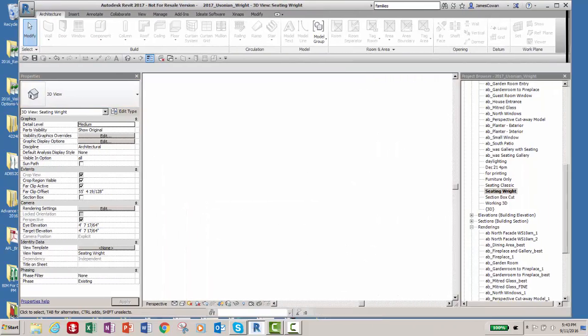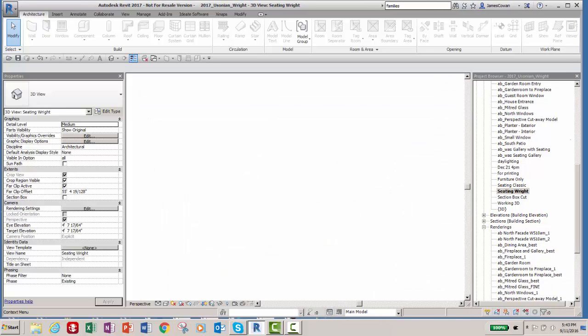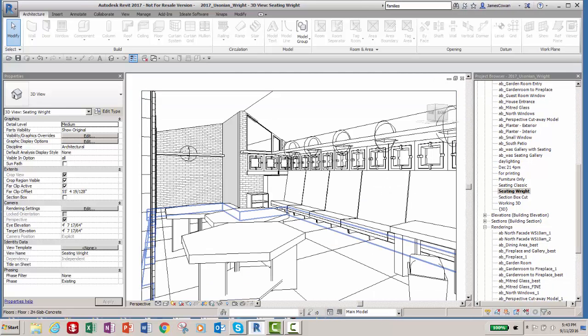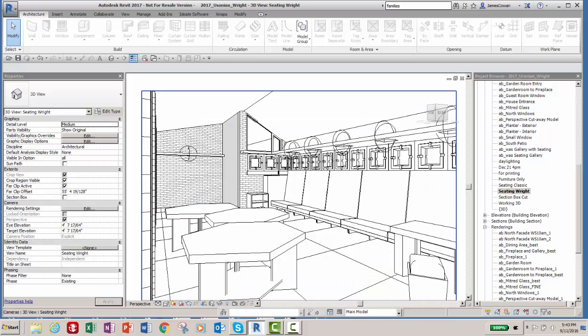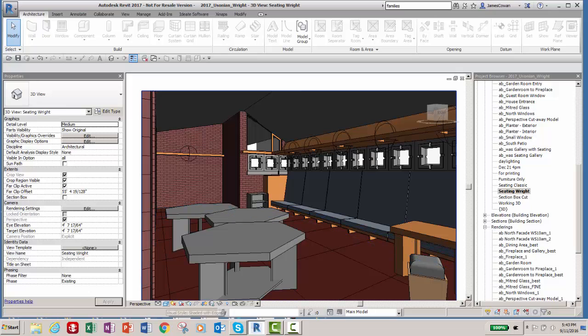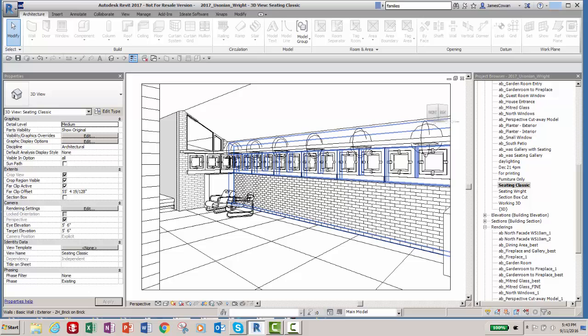You've got the other part of the interface, which is the visibility controls, which is in every view, down here. And these are unique to each view. So you see, for example, if I say turn on shadows, or turn off shadows, or show shaded, or show realistic, that's how I could control the graphic display in a particular view, but each of them is independent